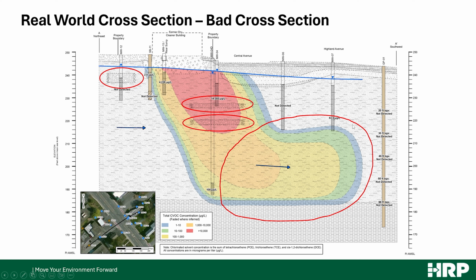What I like to see, and what I try to do in all of our projects, is let's make the cross section, talk about the geology, talk about what we think is going on from a depositional environment, from a standpoint of whether there are disturbed layers with fill, before we even get the sample results back from the lab. So we get back from the field, let's lay out the soil borings, and let's talk about the geology and how that's going to impact contaminant flow, and how that's going to update our initial conceptual site model that we had for putting the borings where they are.